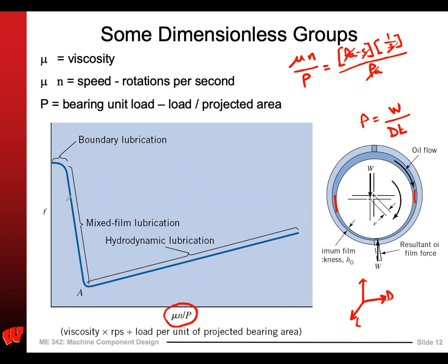So what happens if I said, well, let's say oil stays constant viscosity, say the load stays the same all the time, so just N is changing. So I could say this is example N equals 0, and then N equals fast over here. At 0 speed, metal on metal, a lot of friction, and I start to introduce some oil to the interface. The friction drops.